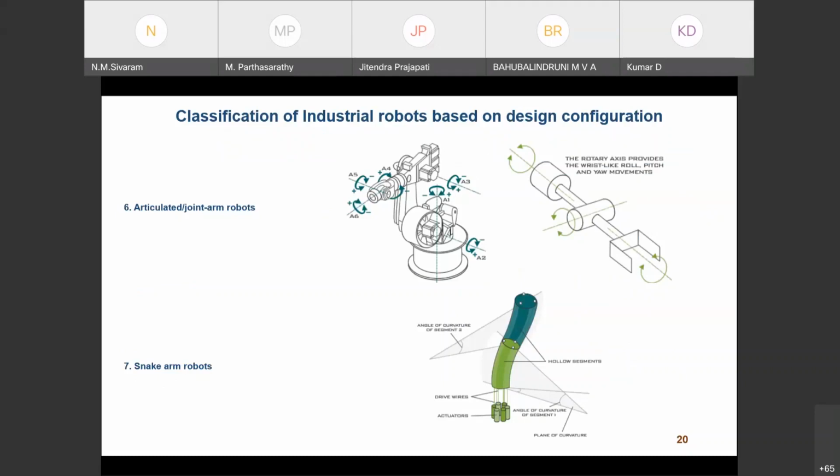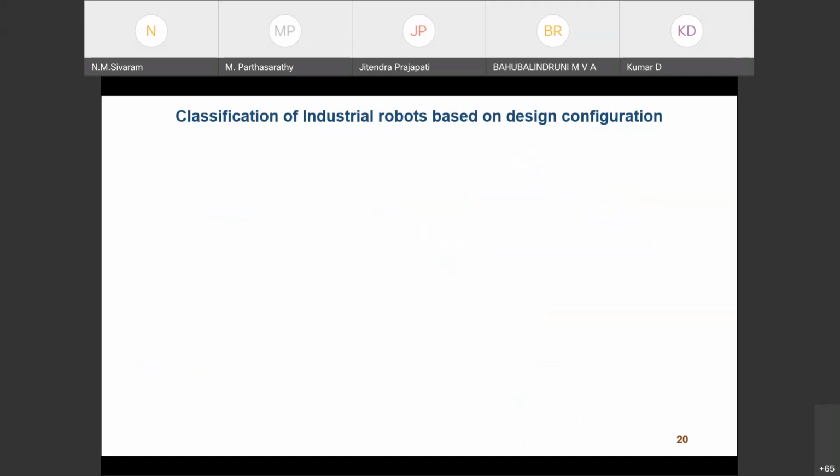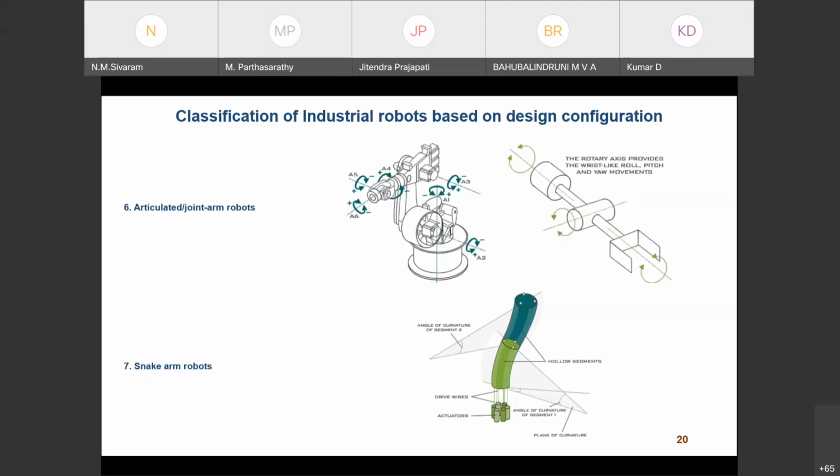So all the robots, if you see, there is this particular work envelope or workspace defined for this robot. So it is very important for the programmer or the operator not to go into that workspace of the robot without any proper safety measure. So that is very clear from defining this workspace. When you know the type of robot you are working with, you should be well aware of its work envelope, because the work envelope is where the robot will have its motions.